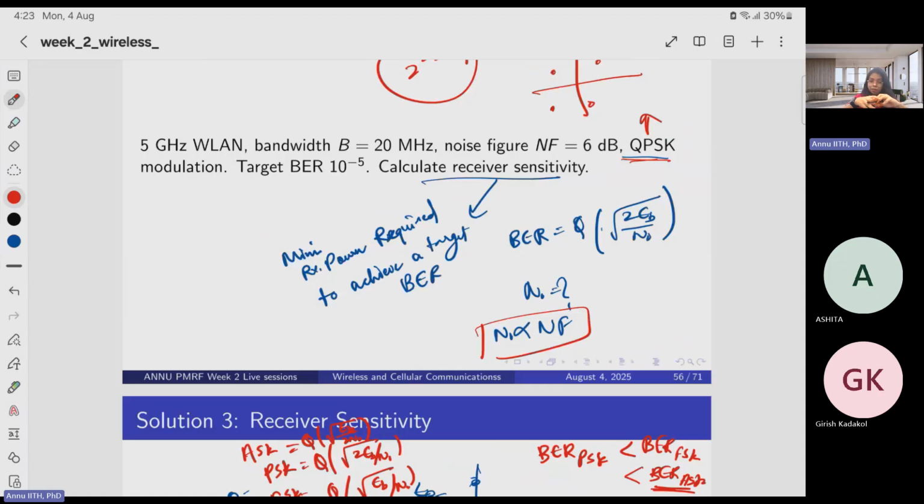So it is actually the measure of how much a device, like an amplifier or receiver, degrades the signal to noise ratio. So it quantifies the amount of noise added by the device, because suppose a noise created by any electronic device is a thermal noise, and it is nothing but KTB. Now you may ask, in that device, what is the scaling factor it gives? So it is given by the noise figure. It should be less.